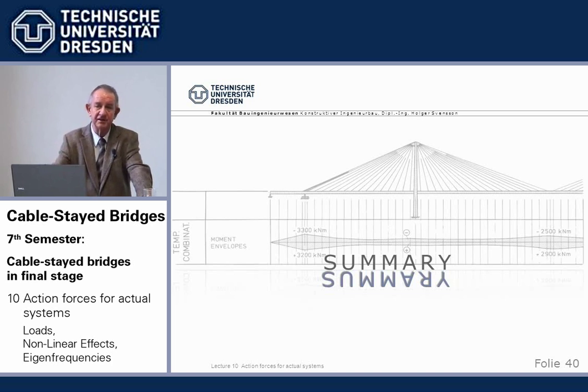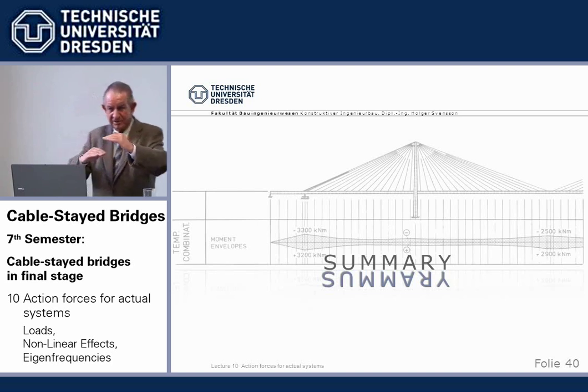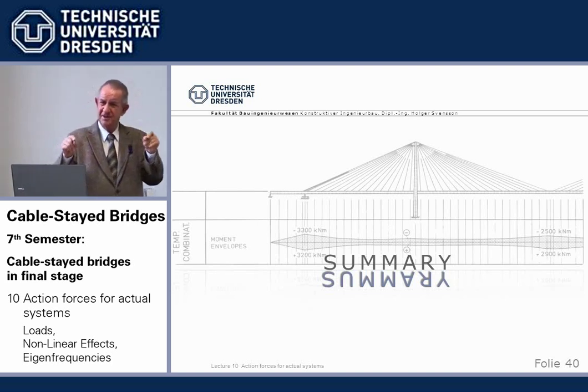Although you will see next time, it's very simple. But what I insist is that you understand the flow of forces. And for example, this increase of second order beam moments in connection with the depths, because that goes in the very first try of the design when you say, what depths, let's make it slender.